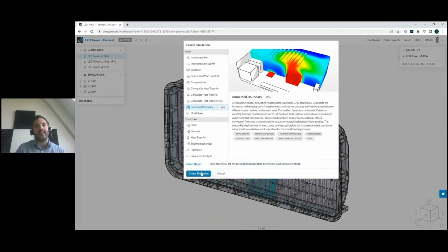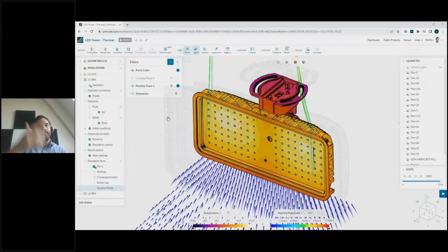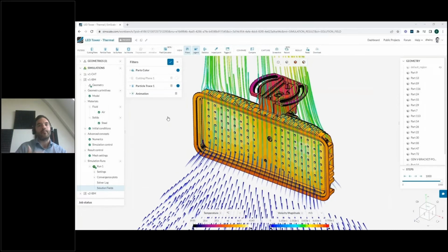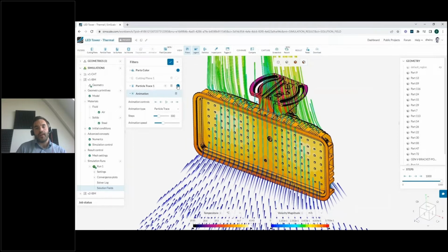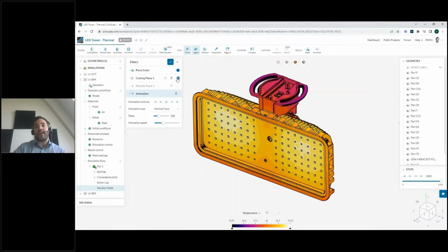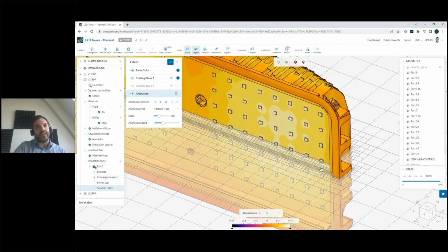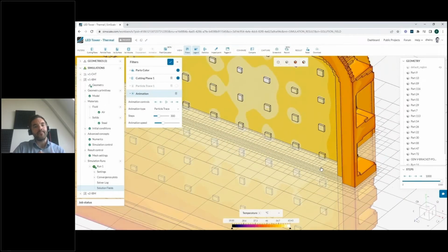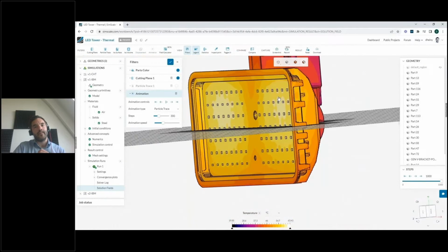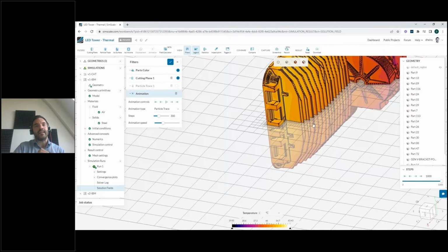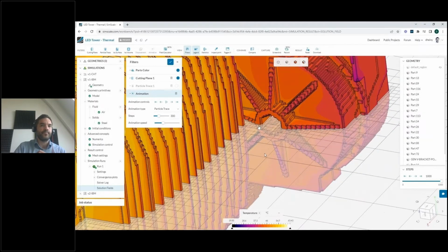Now we can see we introduced an immersed boundary method that is actually able to reproduce the same results. However, it uses a fraction of the cells. So here we can see that the mesh isn't body fitted, but it's immersed and sort of cuts through the boundary. And by that, mesh generation is much faster, much more efficient in terms of cell count.